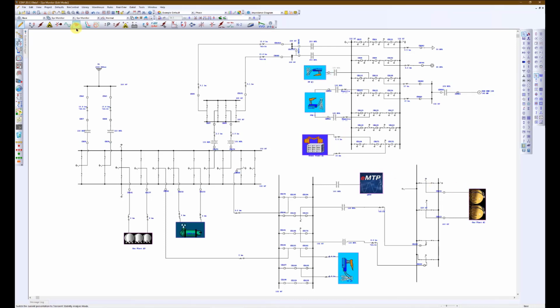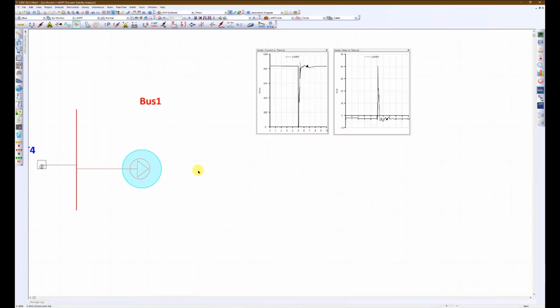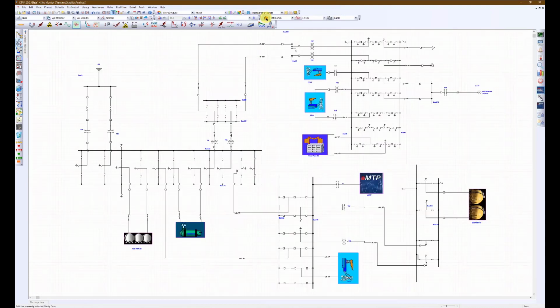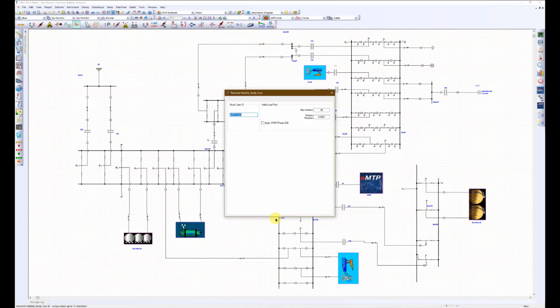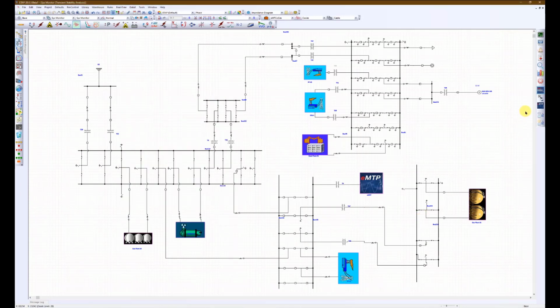In ETAP 20, eMTCoSim analysis is provided for a single boundary block representing the ETAP equivalent network at the CoSim element boundary bus. The wind farm is modeled in this subsystem as a lumped load. The dynamic model in the eMTP domain is used for the co-simulation. The event applied to the phasor domain can be seen in the Event tab in the study case editor, where in this case, a 3-phase fault is applied to the wind farm at 5 seconds and cleared after 100 milliseconds.